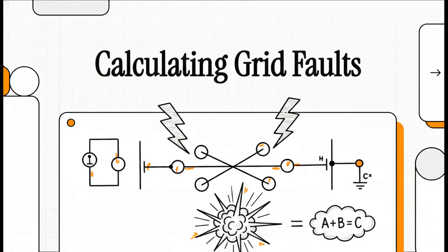Last time, we built the mathematical models, and right now, we are jumping straight into the payoff. Look, if you want to calculate the exact fault currents for any unsymmetrical fault on a power grid, the entire trick comes down to exactly how you connect your sequence networks at the fault point. Get that connection pattern right, and suddenly, the massive, highly destructive, real-world physics of a grid fault is distilled down into, well, just some simple algebra.